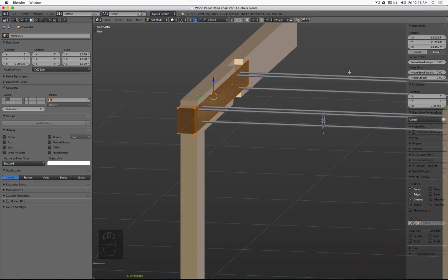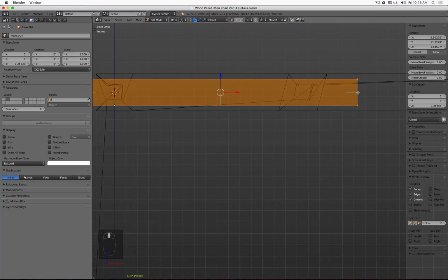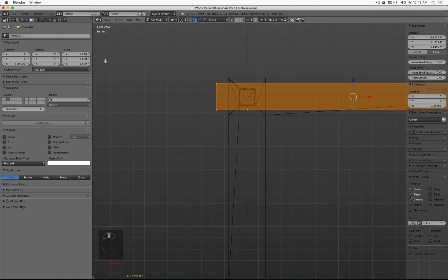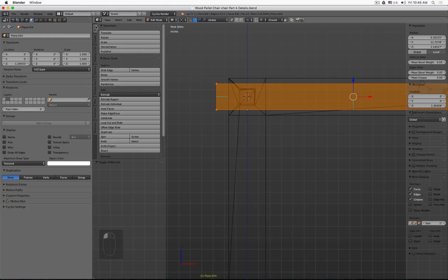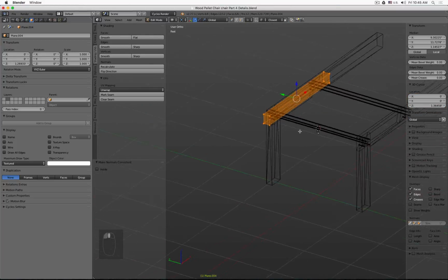When we're in edit mode and we turn on the normals and we take a look, there we can see the normals face inwards. So not good. So in this case, we go to shading and UV, have everything selected, recalculate, and you see they flip outside. We can turn this off and we're good.